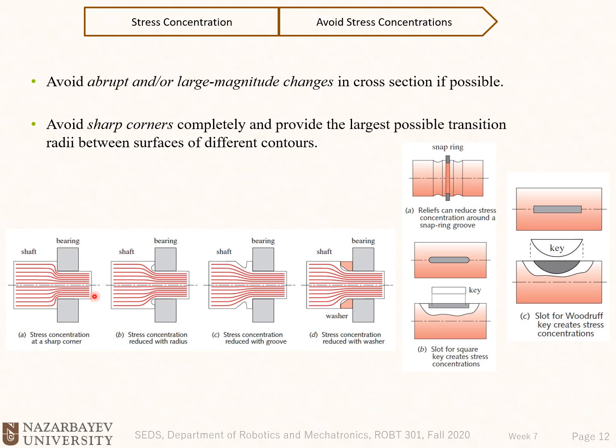So this one is a shaft, and this one is a bearing that sits on the shaft. We need a step to have a place to accommodate the bearing on the shaft, but you see that we could have a different type of mounting, and these different types of mounting will end up with a different type or level of stress concentration. Here they are using a washer, okay, and they have this smooth fillet here that also reduces stress concentration.